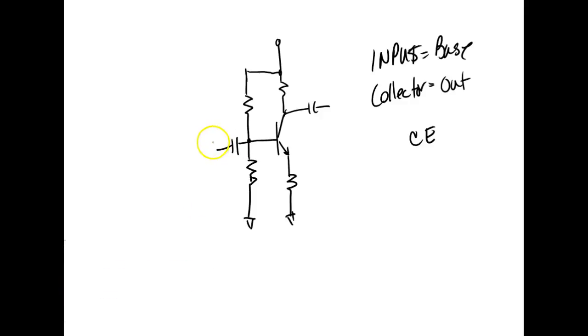So the signal comes in here and flies through here. It goes that way, it goes that way. What does the signal do up here? What does an AC signal see a DC source as? It sees it as a piece of wire. So you can't say it sees it as ground, it sees it as a piece of wire. An AC signal will fly through a DC source like it's not even there. A DC signal will fly through an AC source just like it's not even there.